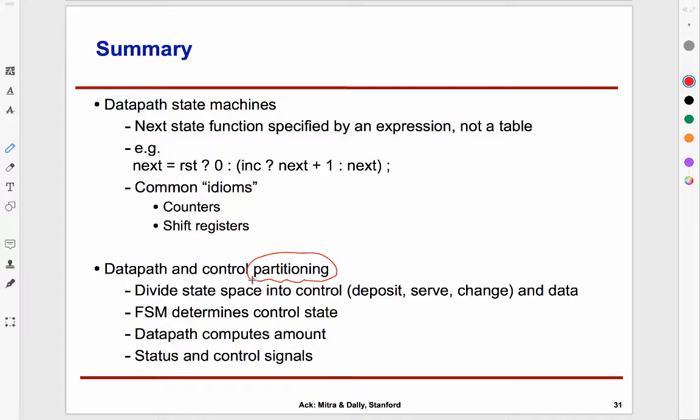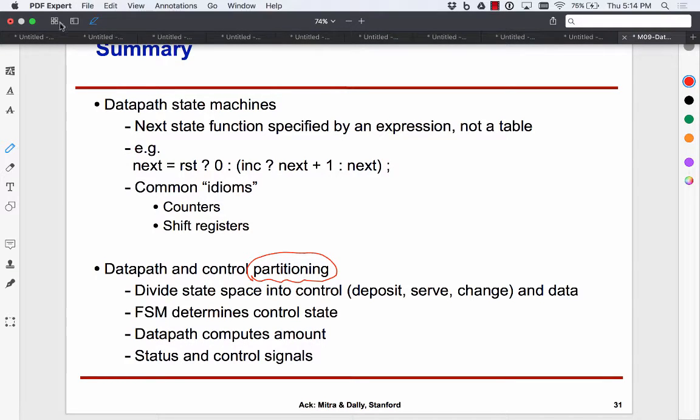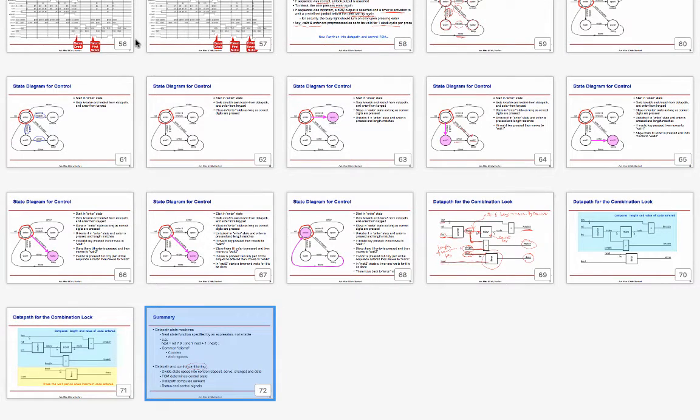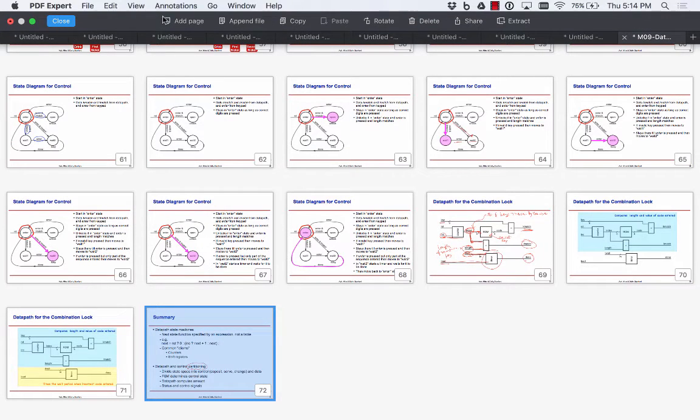What it is really doing is changing a little bit after the clock tick. When the clock tick comes, the state changes. In the diagram, it would appear that the state changed immediately, but it would be changing a little bit after that. Likewise, if there is an input signal coming from a previous stage, it too is changing after the clock tick. Let me try to explain what I mean.